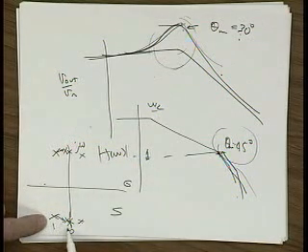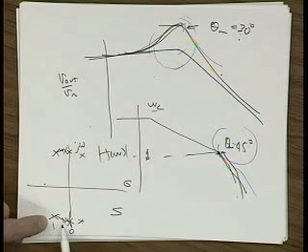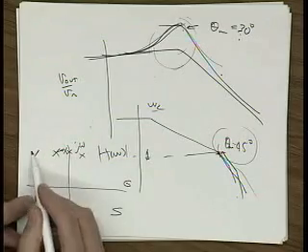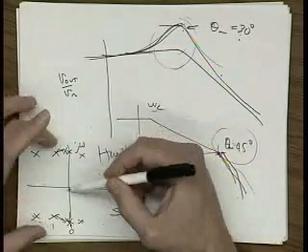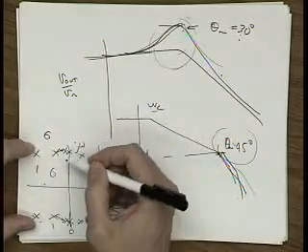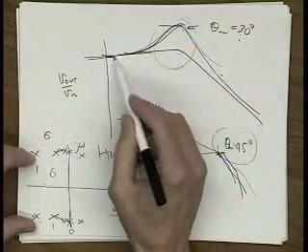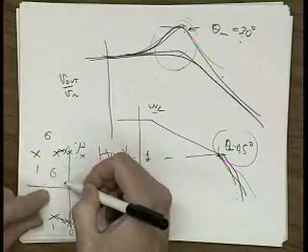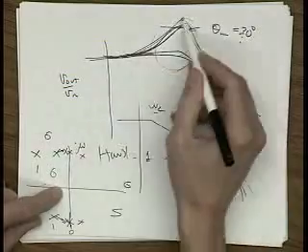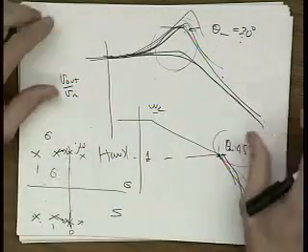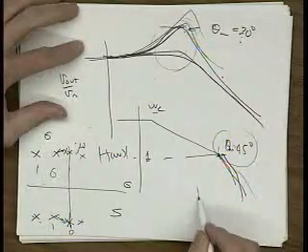So really what's happening as we have less phase margin, the poles are getting closer to the axis. They have more phase margin, they're moving away. If you plot the frequency response for a set of poles which have a real part, this is the real part of the pole, right? As the real part gets larger, you'll see the response has no peaking to it. As the real part gets smaller and smaller, you'll see that these poles have a more and more peaking effect, right?